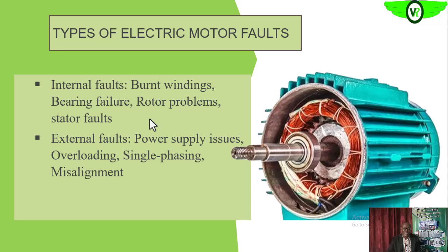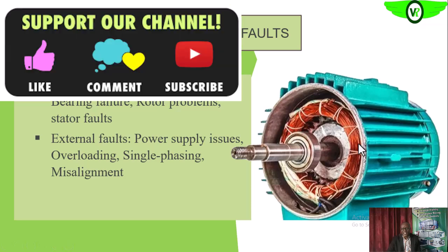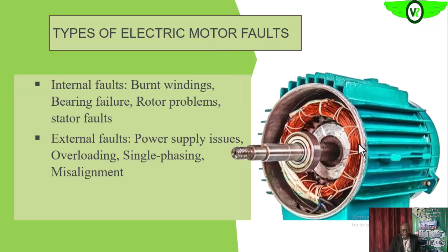Then we are going to look at external faults, or faults that are external to the motor itself. In this case, we'll be looking at power supply issues, that is, the quality of our power supply. If it is not maintained, it can affect the operations of the electric motor. Then single phasing, as we'll see later, which is also a power supply issue, can affect the integrity of the motor's operation.